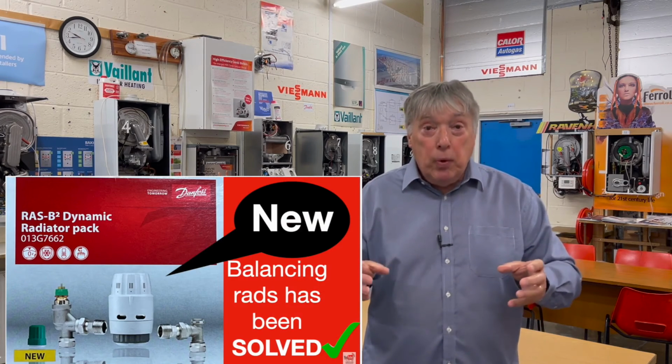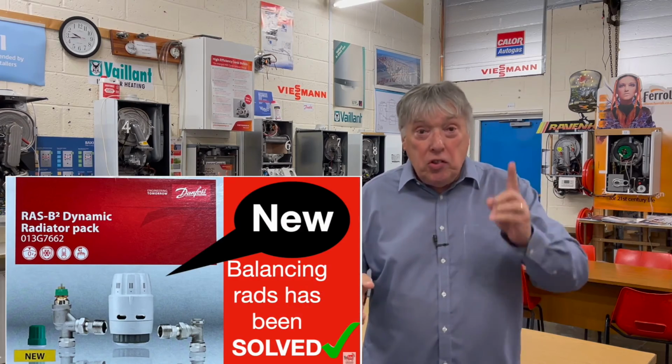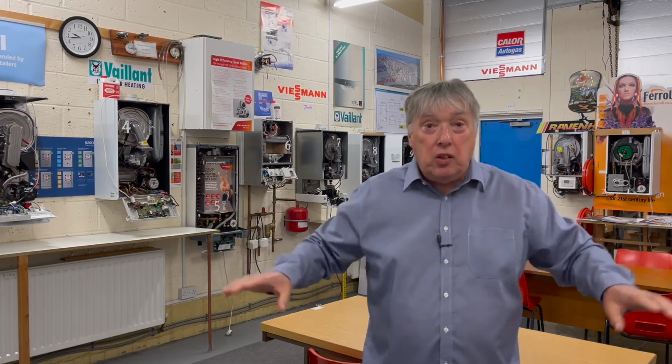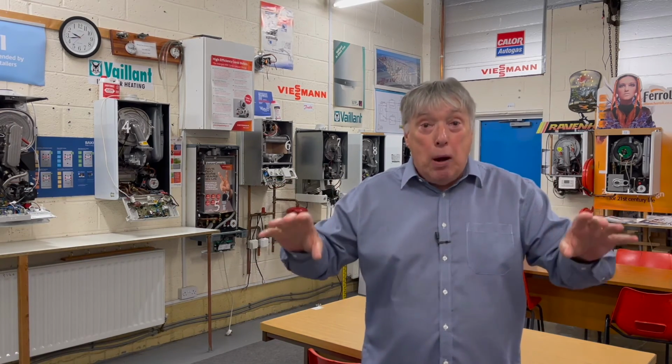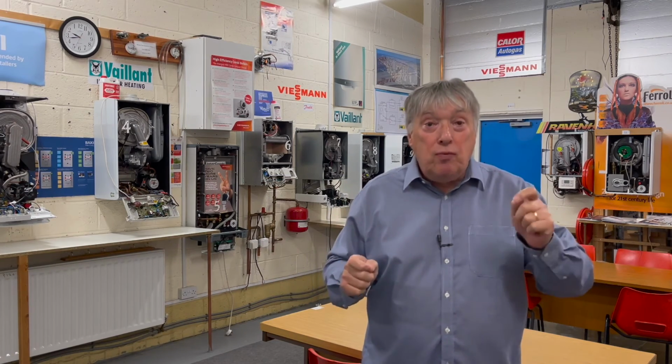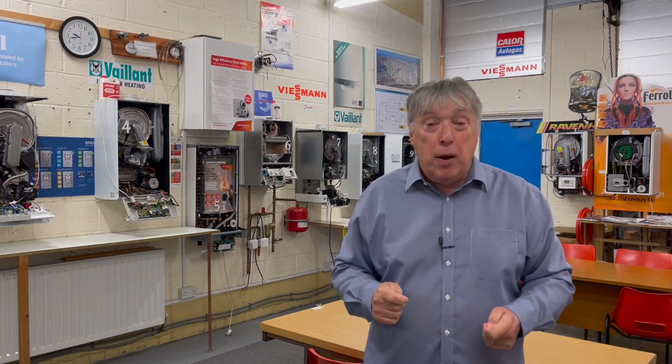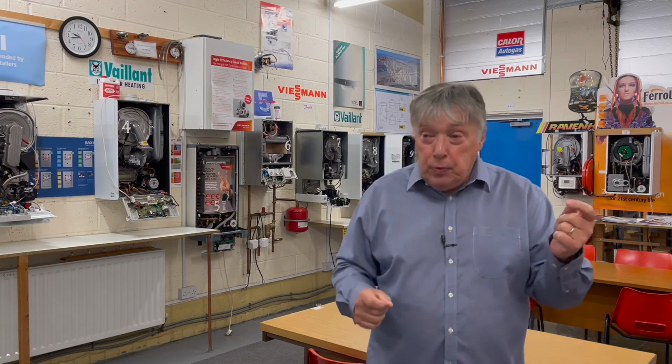Balancing the system is the number one first thing that you should do before anything else. Have all the radiators singing from roughly the same temperature and the same outputs. Then you can fine tune it with balancing TRVs, automatic bypasses, inhibitors, and so on, as I've covered in all the other videos. So download the app, make it easy for yourself, and then see if it's got the right size radiator in that room.